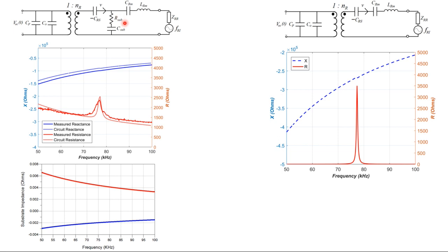The substrate thickness is finite, but much smaller than the operating wavelength of the CMUT. So you can see that the Q is much lower on the left side, in the case of a thin backing.